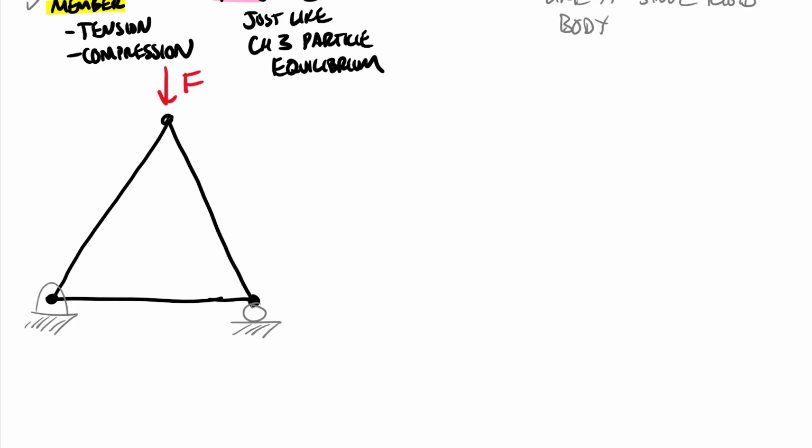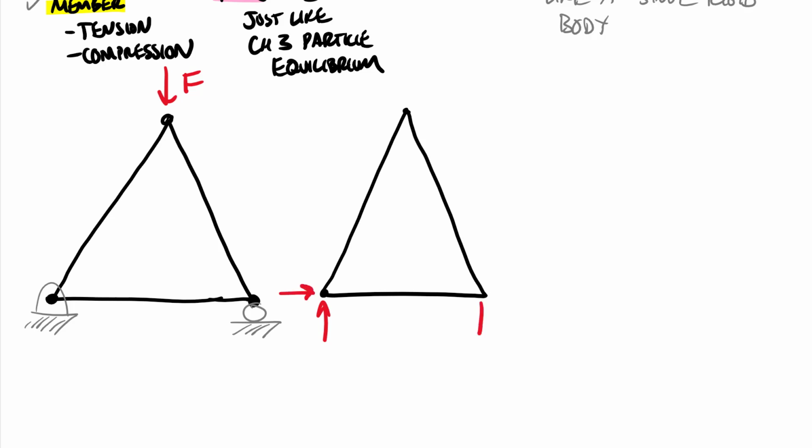We know that if this truss is in equilibrium, we also can draw a free body diagram. That word equilibrium should key in your brain this idea of free body diagrams for every single equilibrium problem. So we add in our unknown supports, roller here with a vertical support normal to the surface, and our applied force F. To complete our free body diagram, let's add an axis system.